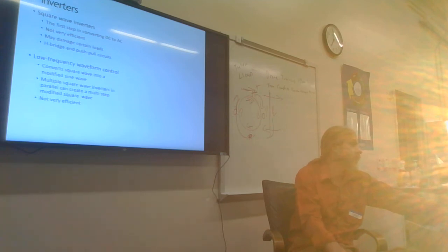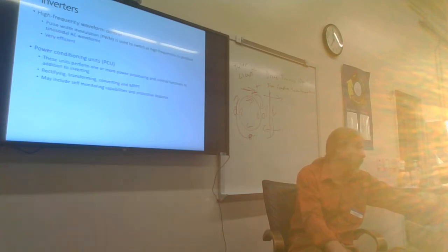So it's possible. I'd almost think the opposite, man. Because you know that those high startup loads have to be induction loads, which means they really need the most sinusoidal waveform possible. So you might make sure you didn't flop that in your brain. Because I would think that high frequency waveform control would be the required one for high startup loads.